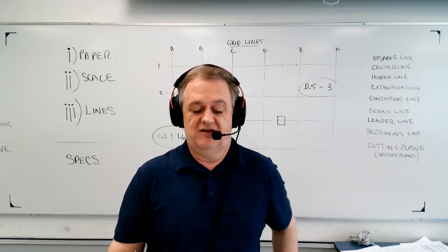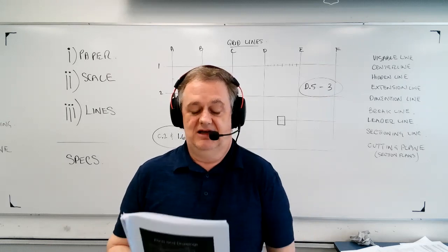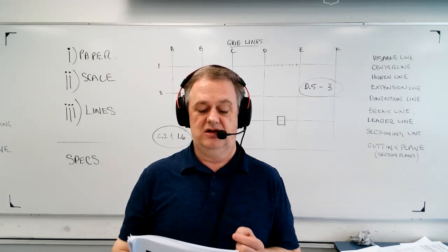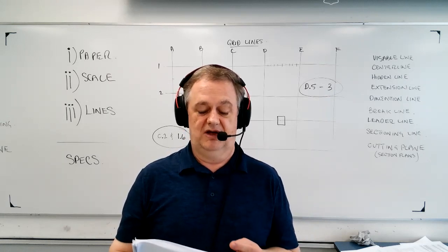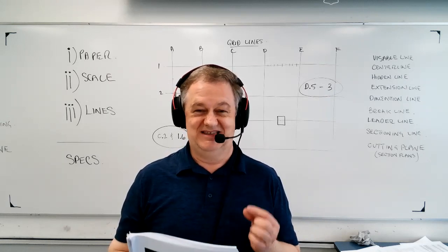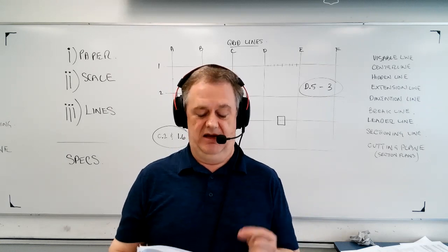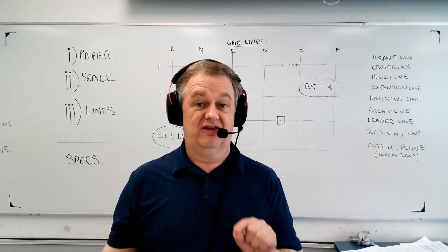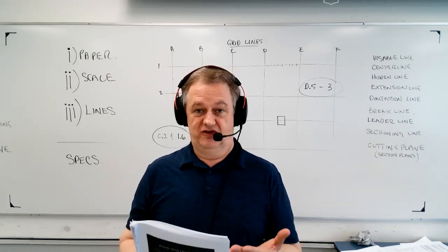But each division is subdivided into three different sections. The first one is general information, then products, and under products, that would be exactly what must be supplied. And then execution, which is exactly how this must be installed, okay?